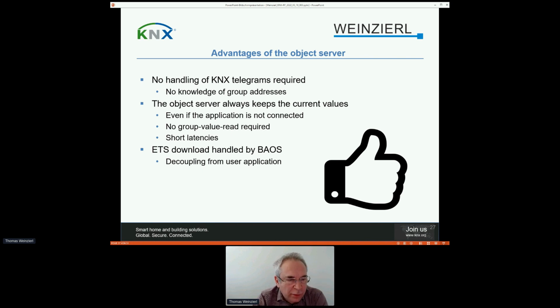And what's of course very important, the complete ETS download is handled by the BIOS module or BIOS device. It is not visible to the client. So you have a perfect decoupling of the user application from the complexity of our KNX network.